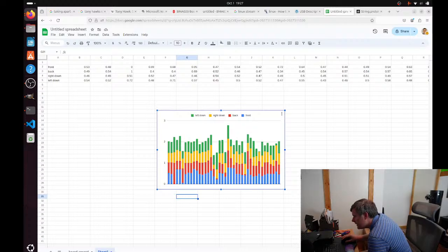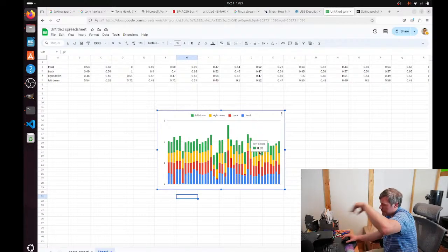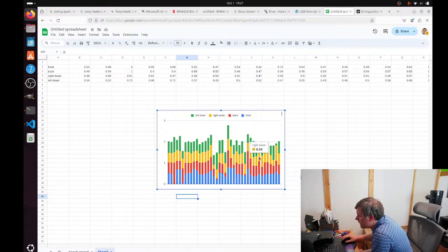Interesting. So this bit is about even when it's flat, although that could just be a bias problem. The fact that it's not always a 1 could just be that the accelerometer is not calibrated, like the center point's not accurate, so I need to do a proper center point. So that would be one bit, some of the information.